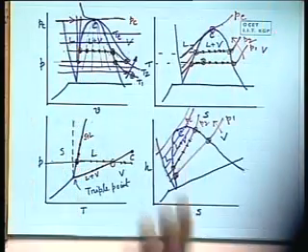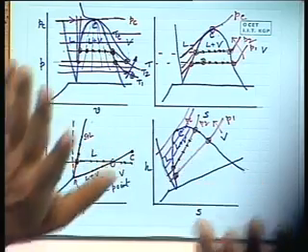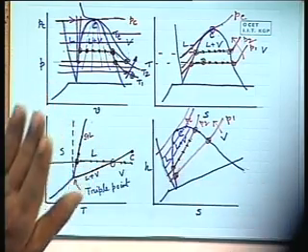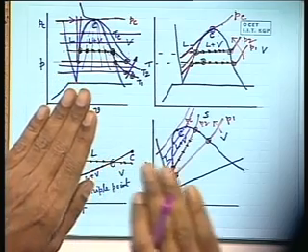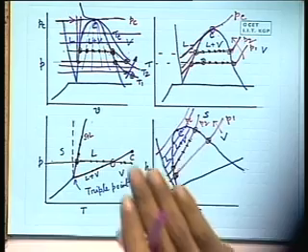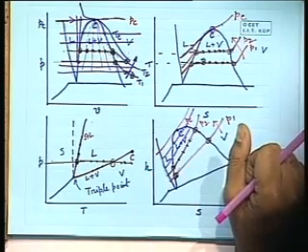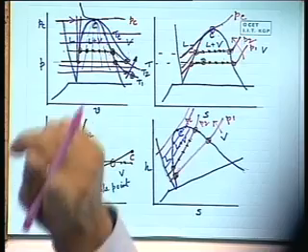Near that temperature, physically the thing is like that. Slowly the density of the water, if you think in terms of one property, specific volume, slowly and gradually changes and there is no discontinuity. That means it is very difficult to recognize liquid from vapor in a distinct transition zone.